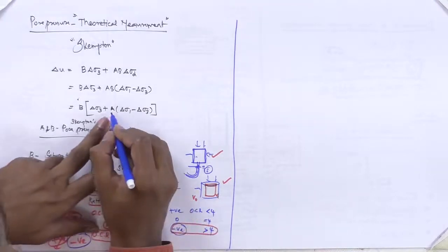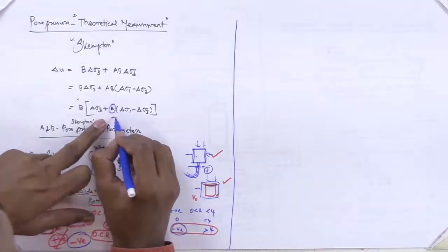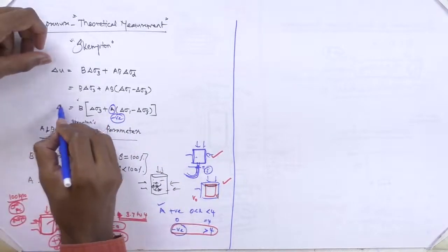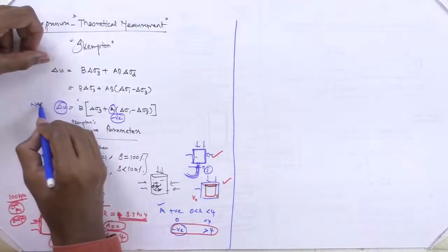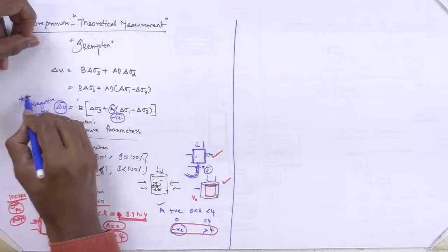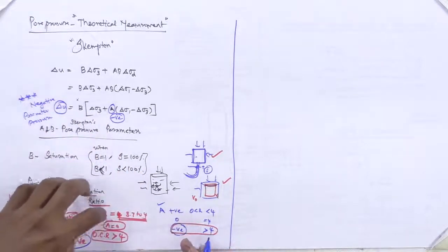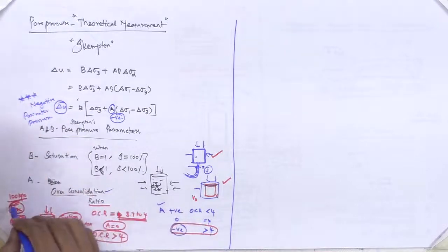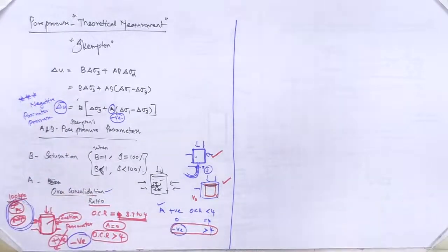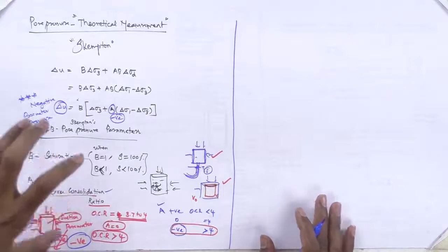So if you apply this negative value here, there is a possibility of negative pore water pressure developing. So this is a major concept. Whereas it occurs only in overly consolidated soil, which is entirely dependent on pre-consolidation pressure. So learn the importance of pre-consolidation pressure here.